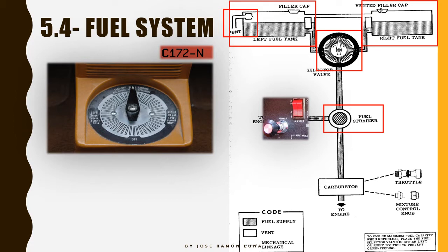It has a lot of air in the lines. So we just squeeze this fuel inside of the lines, inside of the carburetor, and we're going to make this engine start way smoother. We use this in the first start of the day. The rest of them is not required because the fuel pipes are full of fuel, not air.